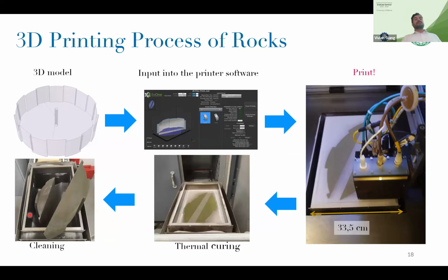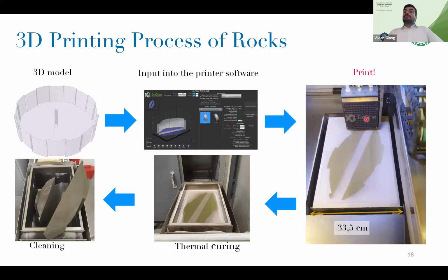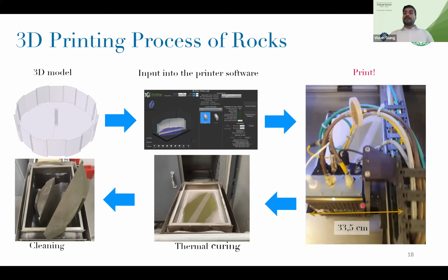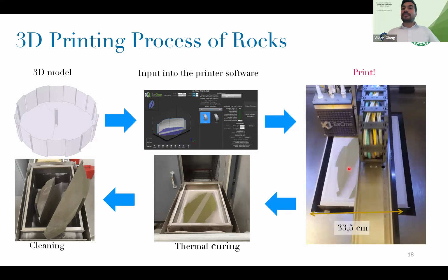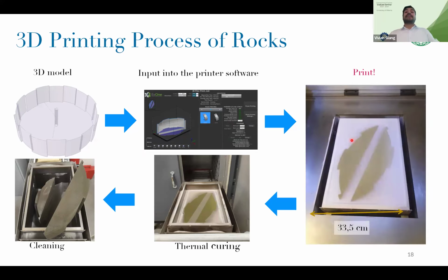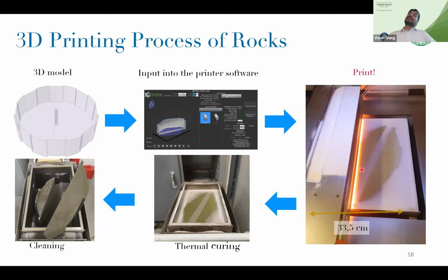How does the 3D printing work? You do your digital design, you go to a slicer, which just tells the machine what to do, and here comes the print. For the print, you can see it's applying a chemical, right? Where the zone that you want, the printer is going. This white thing is just sand, it's just silica. And here comes another layer of clean sand.